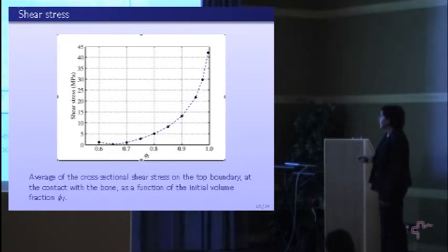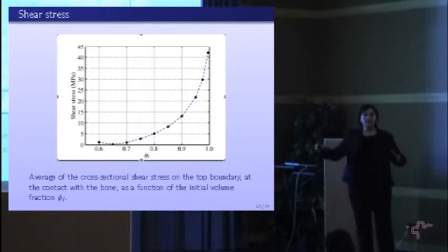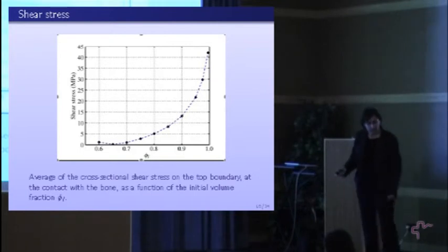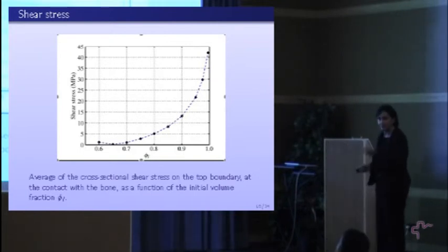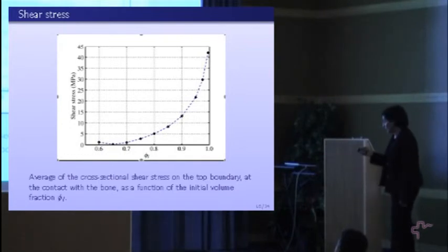So we see that if we have a polymer that is very dry, because phi near 1 means that it will be completely dry, then the drier it is, the higher are the forces that develop at the interface. So it's harder for the gel to really cope with the fluid that it is absorbing.